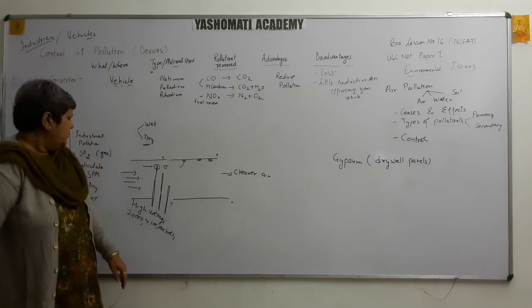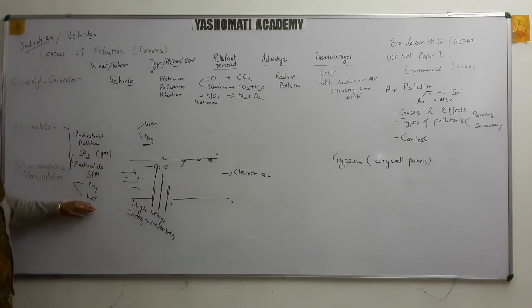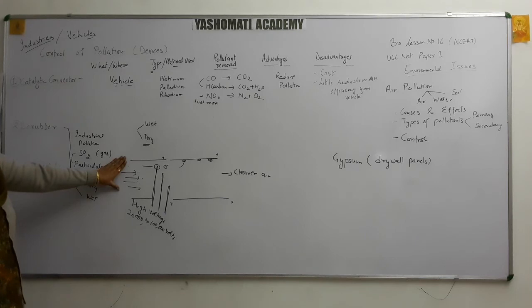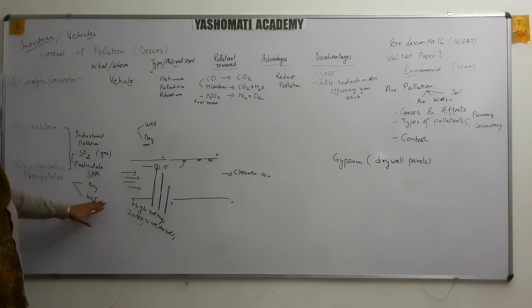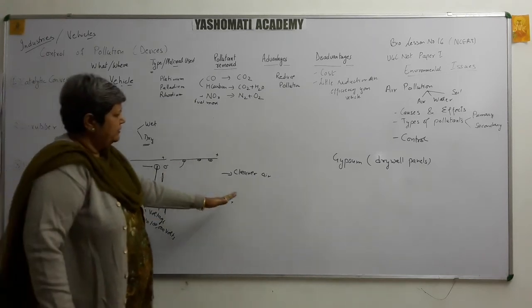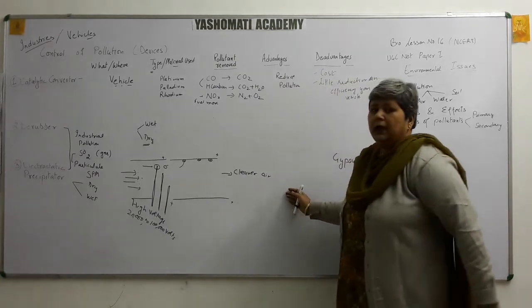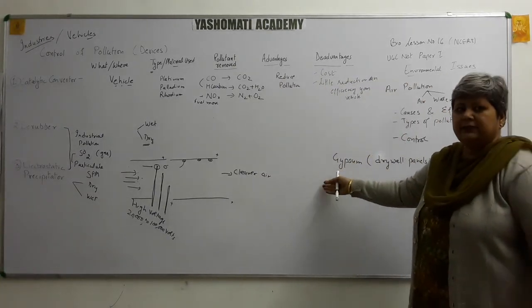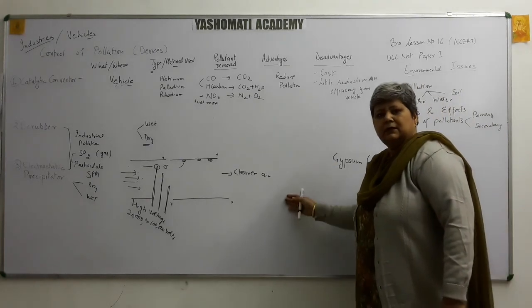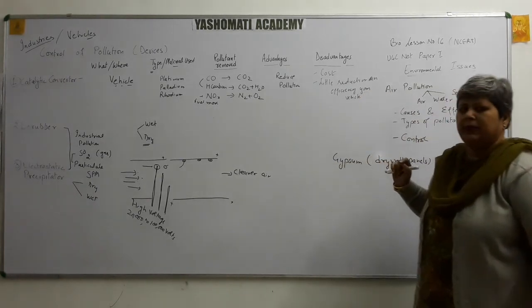So that means wet electrostatic precipitators are better in removing particulate matter. And even if the substance is greasy, or if the exhaust gas coming out of it is moist, then also wet precipitators are better. Now what are the advantages? We have already discussed that even small particles may be removed, and even if the particles are greasy or the gas is moist, even then it can be made clean.